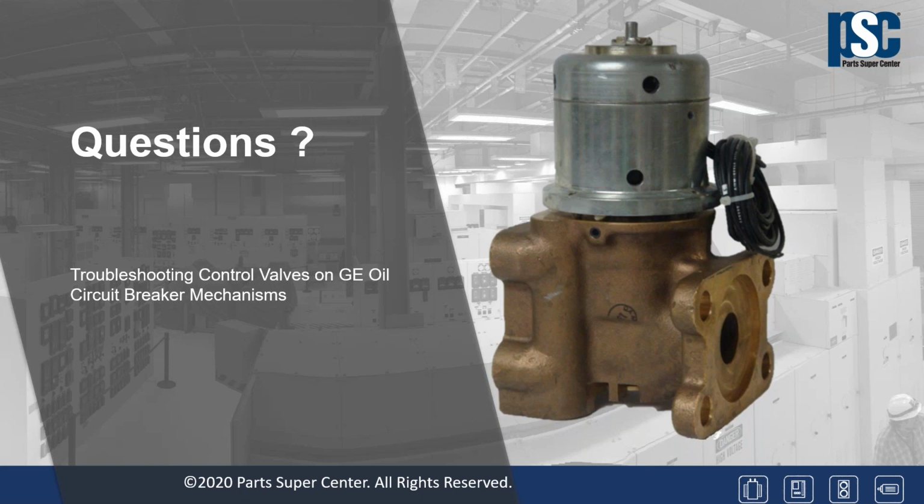Okay, we have another question. How can I adjust the opening time? The opening time of the breaker is not related to the control valve. So the control valve will change the closing time of the breaker. I'll answer that question, but I'll speak a little bit more about the closing time of the breaker and how it relates to the control valve.